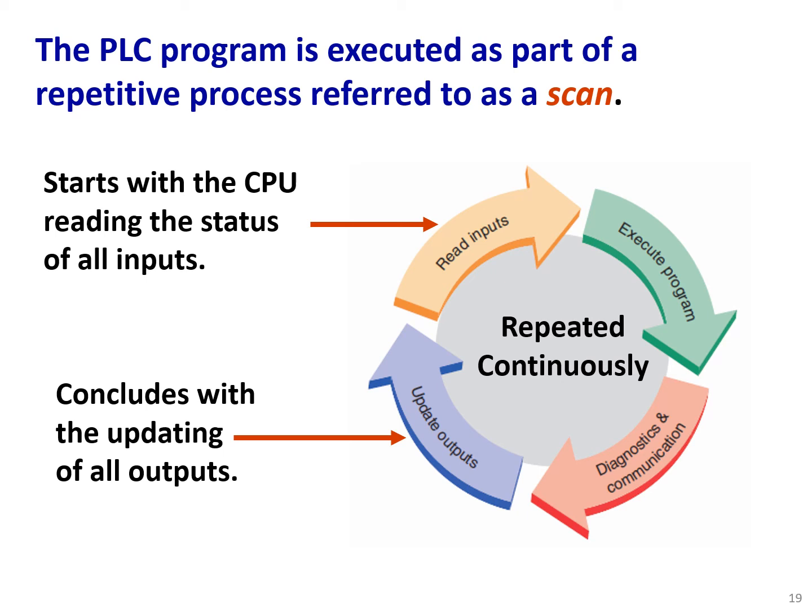The PLC program is executed as part of a repetitive process referred to as a scan. So we have a repetitive process, and we call that repetitive process scan. That process starts with the PLC reading the status of all inputs. So here, this is the start. We read inputs. We have sensors, we have push buttons. So we need to collect the input.